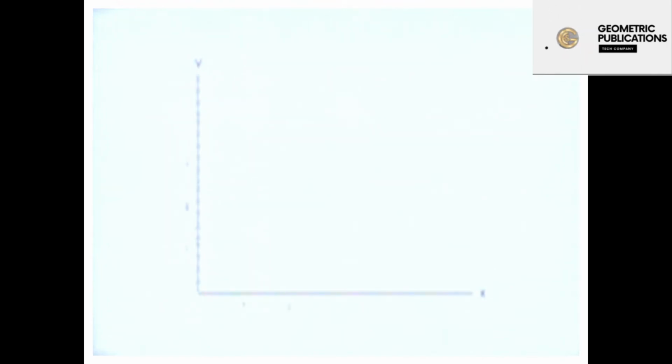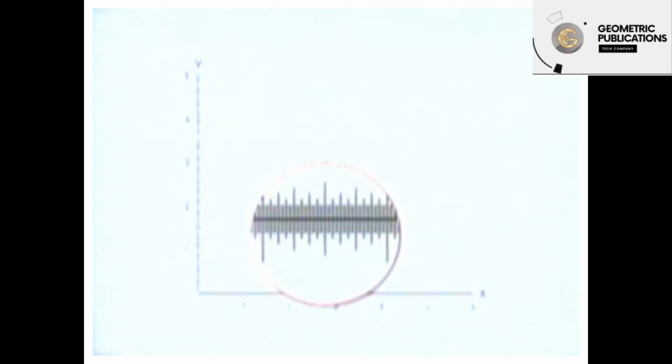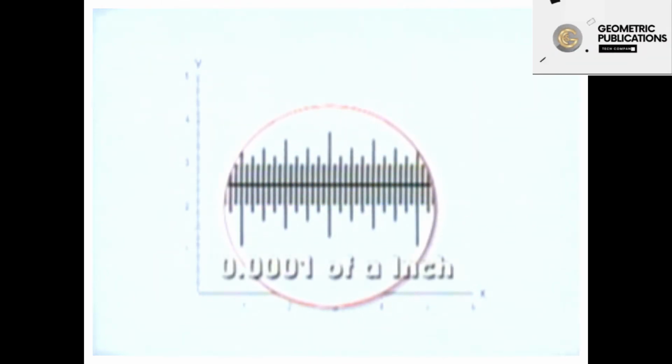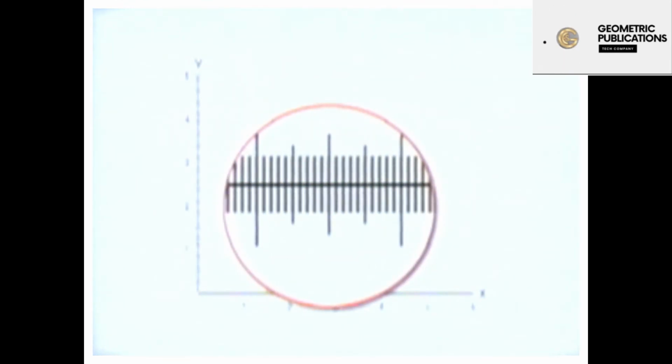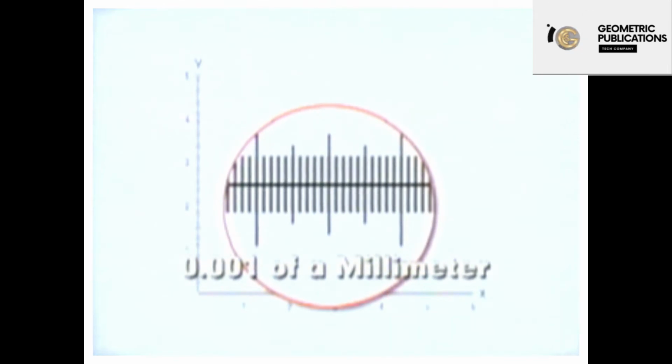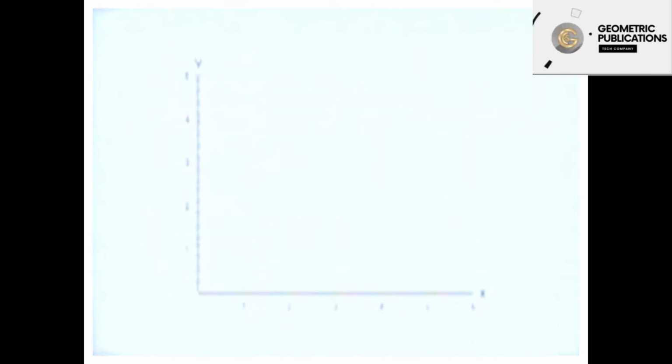Increments for all baselines are specified in linear measurement. For most machines using the English system, the smallest increment is 1/10,000th of an inch. For machines using metric, the smallest increment is usually 1/1000th of a millimeter. The rectangular coordinate system allows the mathematical plotting of points in space, called coordinates, among 2 or more machine axes.